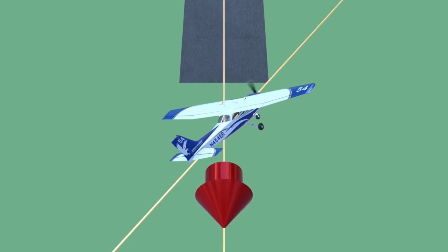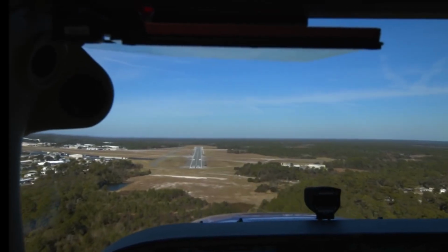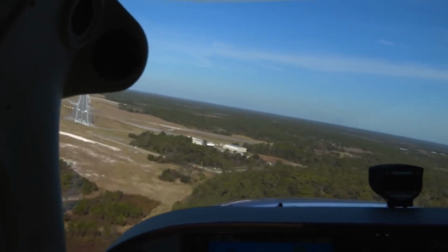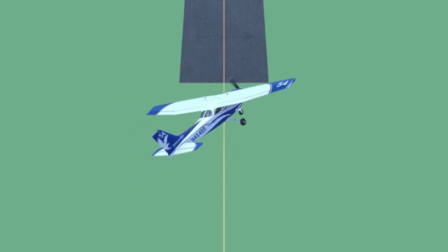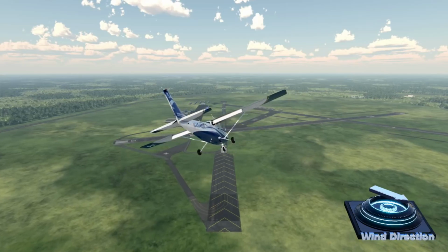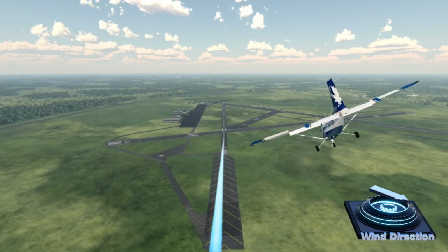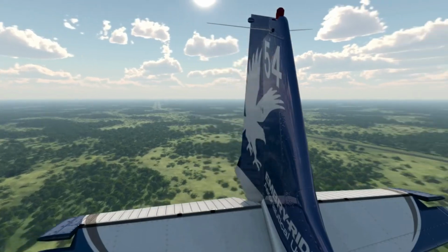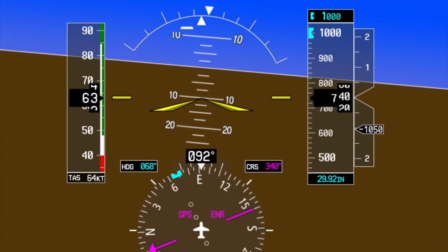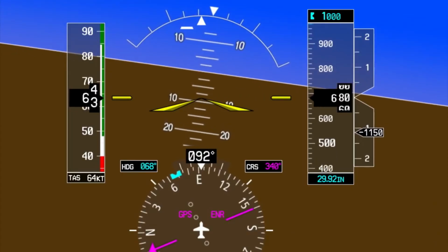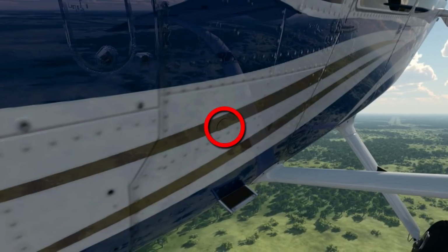Common errors. Common errors with forward slips to a landing: 1. Incorrect pitch adjustments that result in poor airspeed control. 2. Reacting to erroneous airspeed indications. 3. Using excess power while trying to lose altitude. 4. A slip in the same direction as any crosswind. 5. Poor glide path control. 6. Late transition to a side slip during landing with crosswinds. 7. Landing without the longitudinal axis parallel to the runway. 8. Landing off the center line.